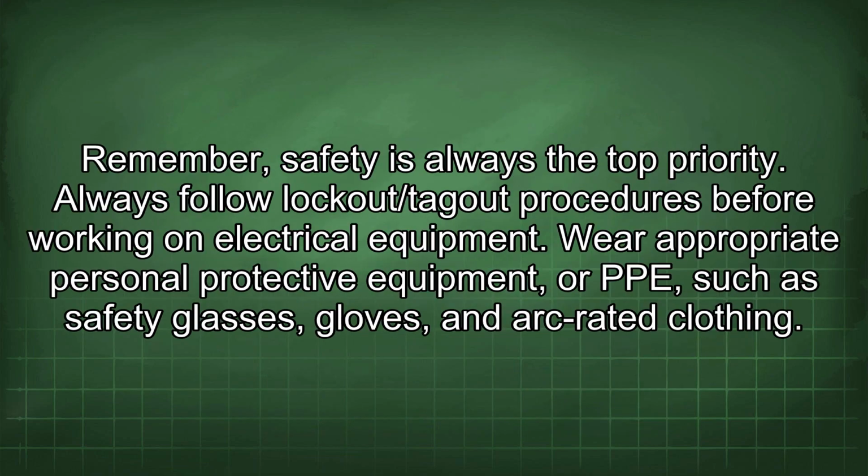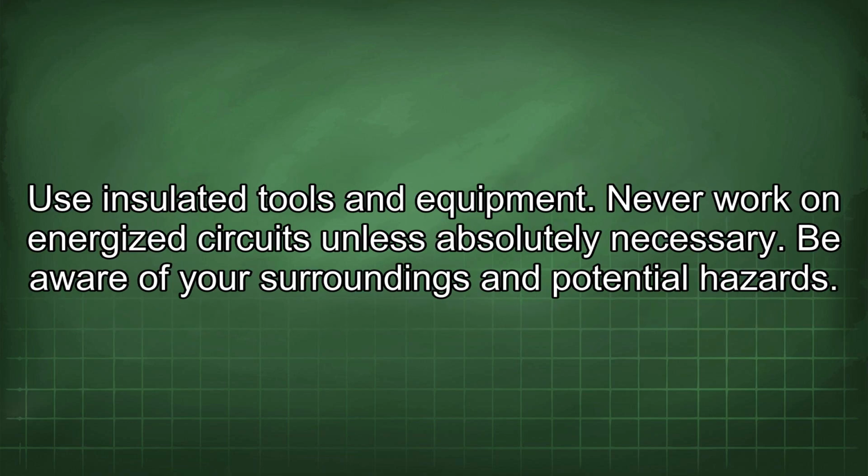Remember, safety is always the top priority. Always follow lockout/tagout procedures before working on electrical equipment. Wear appropriate personal protective equipment, or PPE, such as safety glasses, gloves, and arc-rated clothing. Use insulated tools and equipment. Never work on energized circuits unless absolutely necessary.